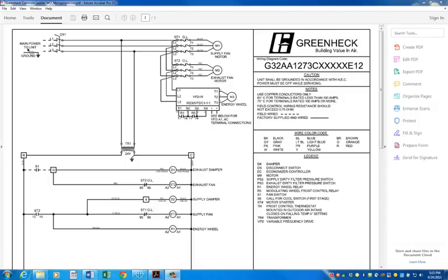This is main power 2 unit. You can see we have L1, L2, and L3. This is a disconnect switch. Okay, very similar to what we learned before. And then the lines go to a motor starter through some overloads to a supply motor fan.